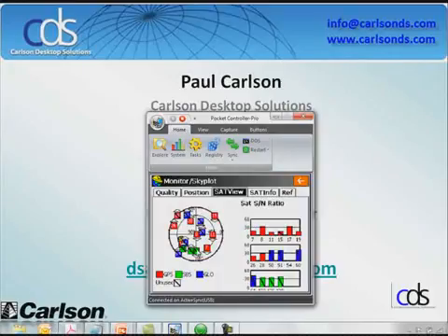Now, I'm connected to the network. My GPS receiver is GLONASS capable. Why am I not getting those GLONASS? Well, in order to receive GLONASS, both the base and the rover have to be able to receive those GLONASS satellite data. In this case, the base I'm connected to on the network is not GLONASS capable. So because my receiver is, if that base is not, I will not take advantage or get to use those GLONASS satellites.